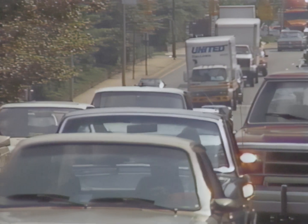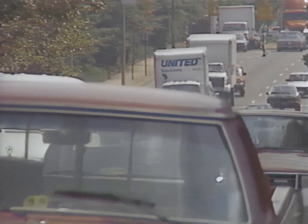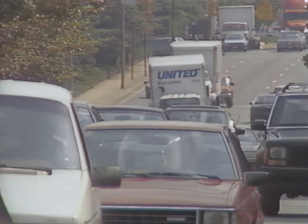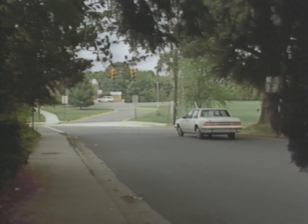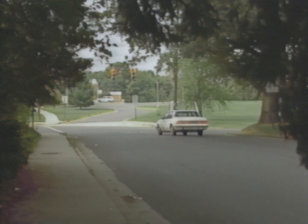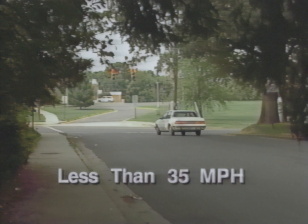Several actuated controllers are capable of providing 2 maximum intervals per phase, allowing more flexibility during peak traffic periods. In addition to phase timing, you must consider the speed of the oncoming vehicles. Approaches of less than 35 miles per hour are considered low-speed approaches. Approaches of over 35 miles per hour are referred to as high-speed approaches.